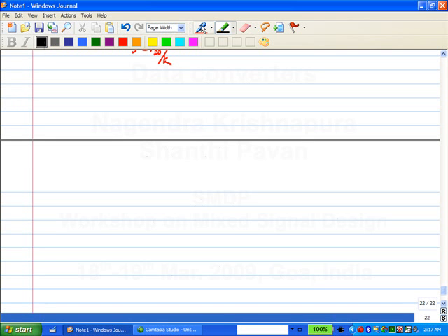Typically it is always that you are given an input, right? And in analog form, if the input exists somewhere, what does it mean? In other words, if you want to store something in analog, what will you do? If you have a voltage and you want to store it and come back later and see what the voltage was, you hold it as a charge on a capacitor.